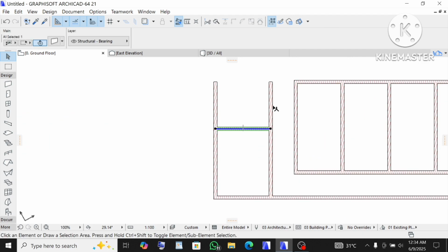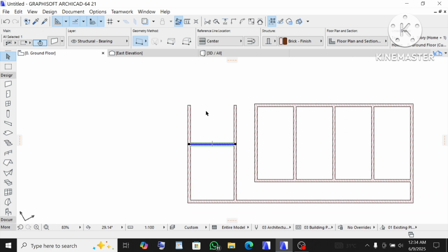So click on that wall. Alright. Press Ctrl Shift D on the keyboard. Click, take it up, and remember the width of the restroom is 900. I will add my wall thickness to it, which would be 1125. Then press enter. And I will also press Ctrl Shift D again for the other restroom. Click, take it up, type 1125 and press enter.